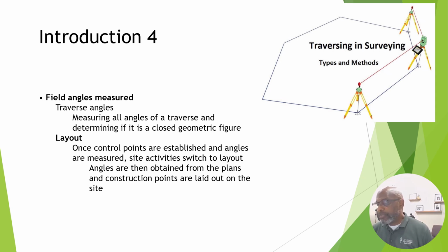Although most points will be laid out with a single direct angle, it is good practice to use the direct and reverse procedures for layout of important points, such as the center of a bridge, abutment, or an elevator shaft on a building, or a stairwell, something that must be in an exact location. So again, multiple measurements are necessary.